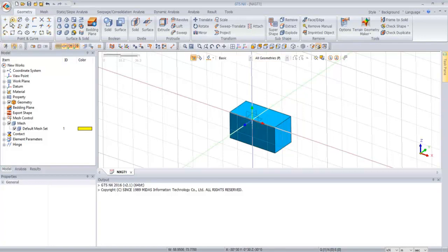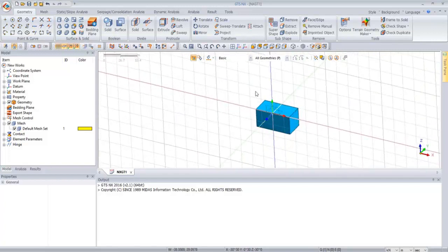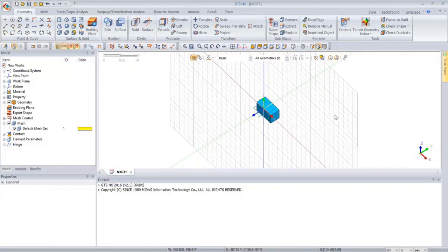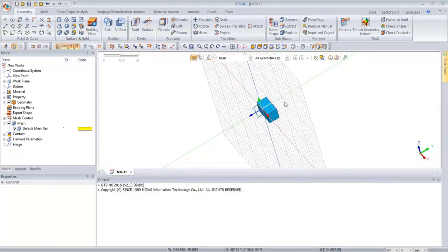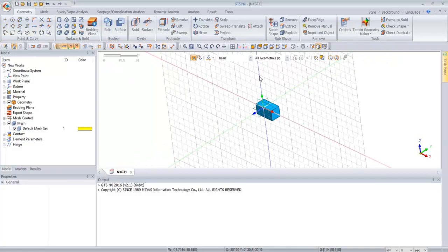Now we're going to draw the location of the pile. For things that are 3D solid geometries, you can drop them anywhere you want. But when you're drawing 2D, we have what is called this work plane. You can kind of see that it's here on the ZX plane. So if I want to draw something, it's assisting us since we're working in a 3D environment. It would be very hard without something like a plane to draw something two-dimensional and be able to distinguish the depth of where we want it to be. So this plane helps us for that.